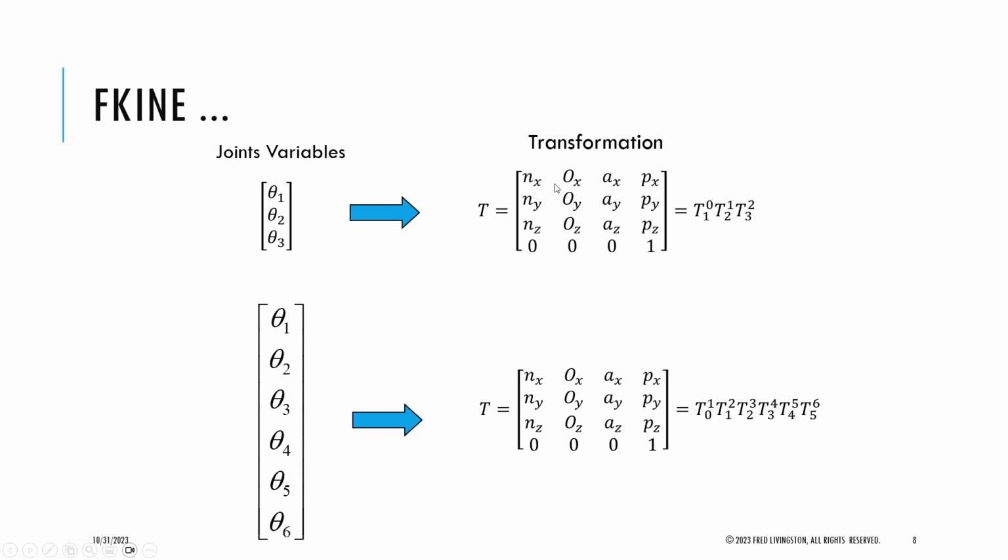A 3x3 matrix can stand for roll, pitch, and yaw, or a quaternion, or any other Euler. And this is going to be your location: the X location, the Y location, and the Z location. And this is always going to be a 1 to make it a square matrix. We would have had a 4x3, and you want a 4x4 because you want to invert this matrix, so we had to make it a 1.